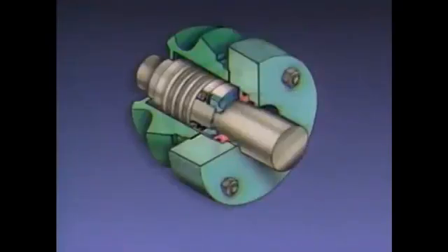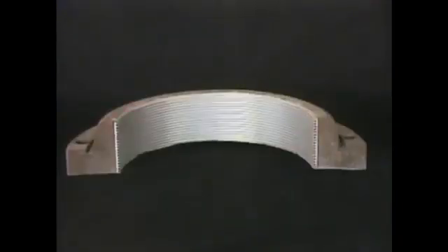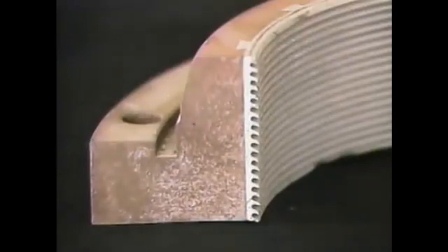The next components we'll look at are seals. Several types of seals can be used to prevent leakage inside a compressor and out of a compressor. A mechanical seal consists of a rotating element and a stationary element that can be used to form a seal between a rotating shaft and a stationary housing. A labyrinth seal consists of a series of ridges that create an intricate path that makes it difficult for leakage to get through the seal. This is a cutaway of part of a labyrinth seal.